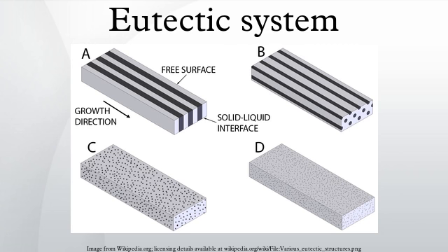Ethanol water has an unusually biased eutectic point, that is, it is close to pure ethanol, which sets the maximum proof obtainable by distillation. Solar salt, 60% NaNO3 and 40% KNO3, forms a eutectic molten salt mixture which is used for thermal energy storage in concentrated solar power plants.